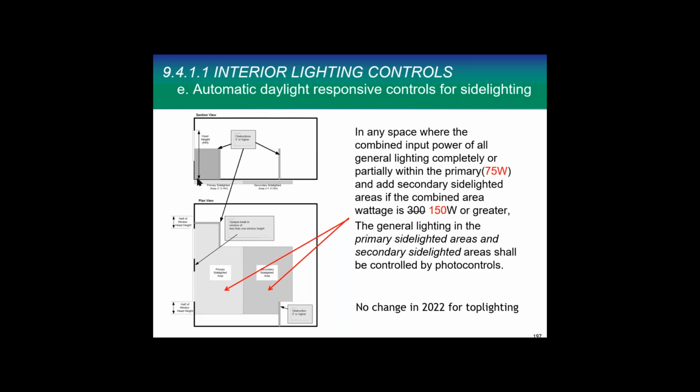It's the distance between the floor and the top of the window. You lay it down. That's your primary area. If there's a block, like a wall over here, and this window couldn't go that deep, it's okay, you just block it off. Now, you have to take that same length and lay it down again, and there's your secondary sidelight area.